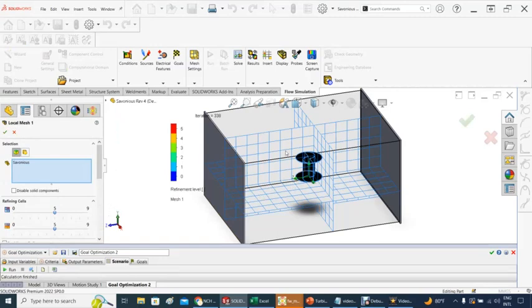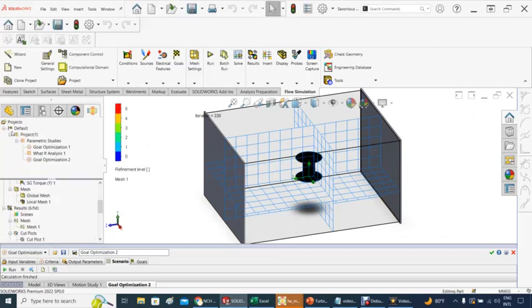You can get to 9, but that's very tiny, what you will be watching here within the refining of those cell sizes. For example, that one is the level of refining for the fluid cell near the solid, in this case the turbine, and the second one is the level of refining of the fluid cell at the solid boundary. So that gives you an idea of where we are on this Savonius testing of the fluid flow dynamics and how that will look. So I'm out of here, and let's see what else we have.